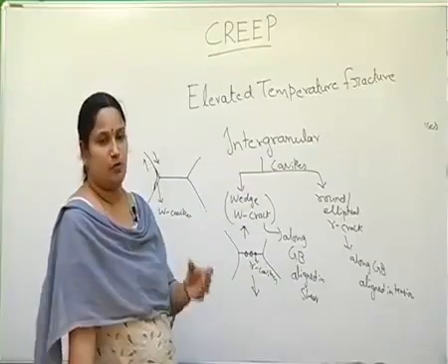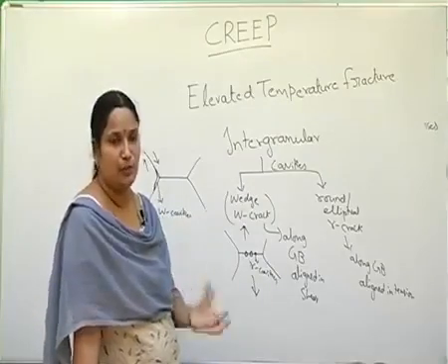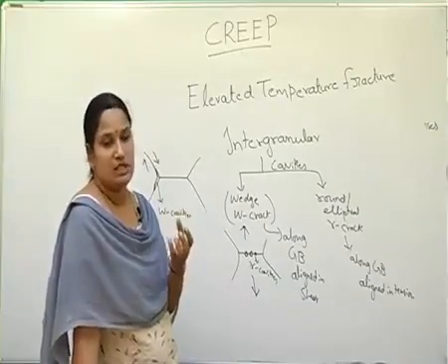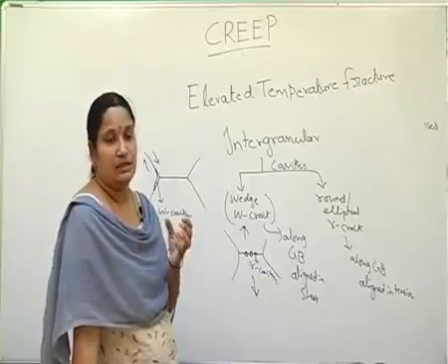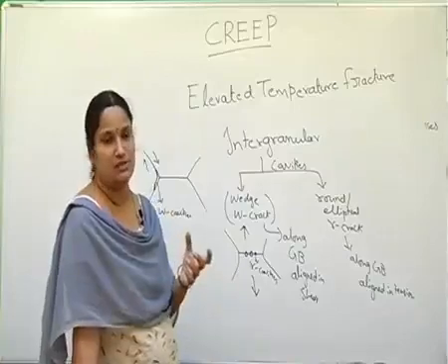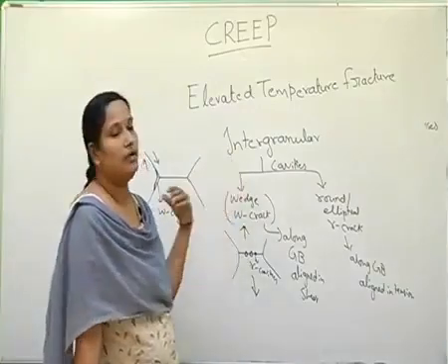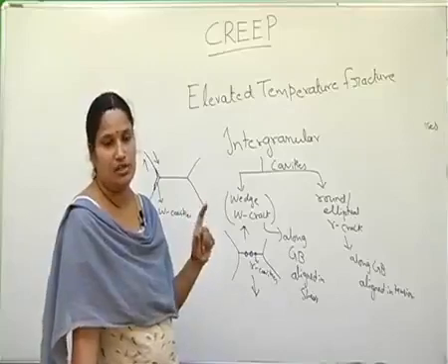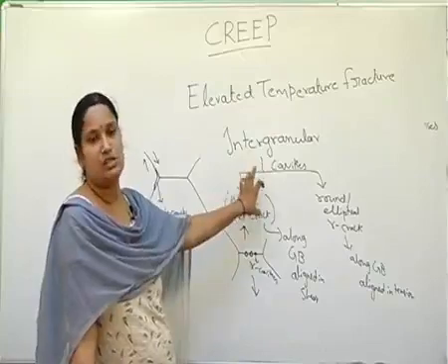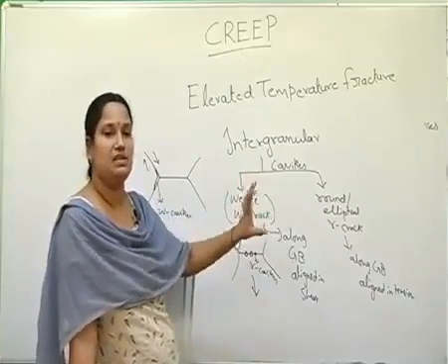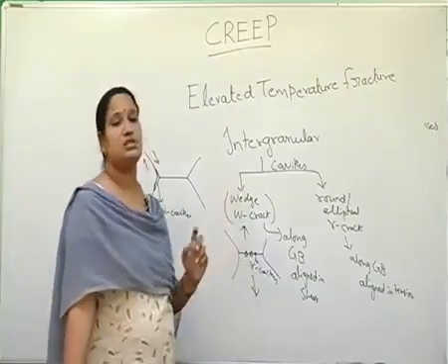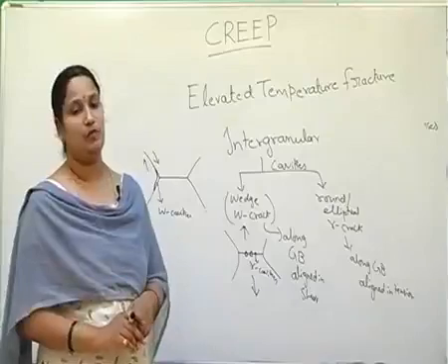Whereas in the case of transgranular fracture mode, the grains in the vicinity of the fracture surface are elongated, indicating that there is no evidence of recrystallization. In intergranular fracture the grains appear equiaxed, indicating recrystallization has taken place, whereas this is not seen in transgranular fracture.